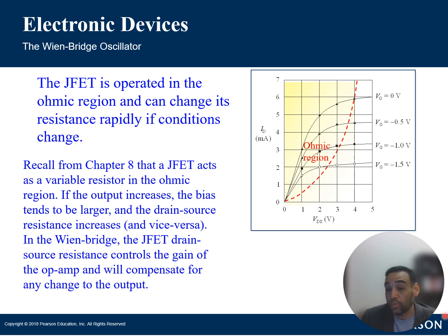If it becomes too high, what happens? Then the JFET enters that saturation region, if you can remember this from your previous courses, chapters. What happens is the drain current becomes relatively insensitive to the changes when it's saturated. In other words, you're not going to get any change in the current with any change in the input. So it becomes useless, and you don't want it running there.